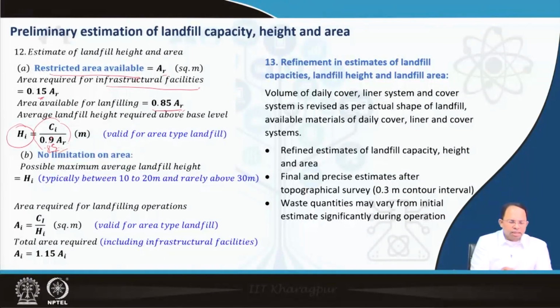So that means the height of the landfill site is determined if I know the area, but this is never the case, right? In most cases, we determine the area which is required based on the design of the height. Now, the height design is based on the profile of the section of the landfill, the groundwater table depth, and many other factors, right? Operational factors and so on.